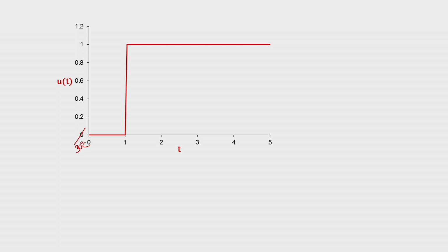Now what is happening? The input that was coming to the thermometer was 30 degrees Celsius till that instant of time, and suddenly it is getting an input which is 70 degrees Celsius. Now how is your thermometer going to respond? If it is, say, a liquid in glass thermometer, then the mercury or whatever thermometric liquid that you have will take some time to respond to this situation.